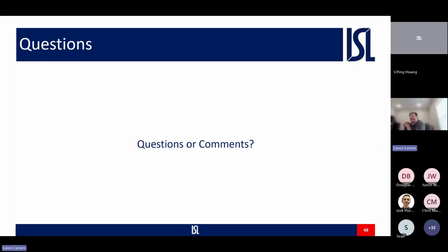Well, so that's it for our PI controller presentation. In essence, the big challenge with PI controllers is figuring out what the proportional and the integral gain should be. We provided some ways of estimating what those are. The negative of delta Y over delta E is a good estimate for proportional, to get you in the ballpark.